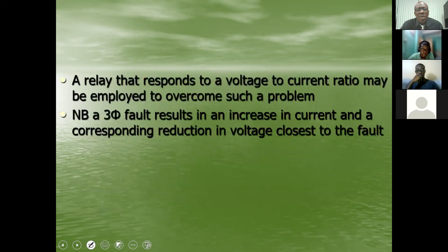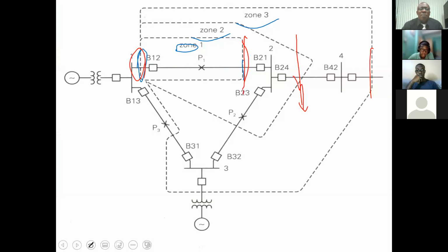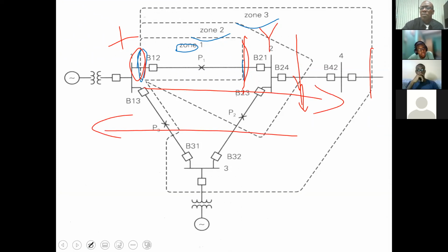And one of the other things I want to mention here is that whilst you have one impedance relay at point X, you're then going to have one at point Y at the other end of the line looking in this direction. So this one will only look down the road. This one is looking up the road. By doing that, they are overlapping. So it means that the entire road is covered.